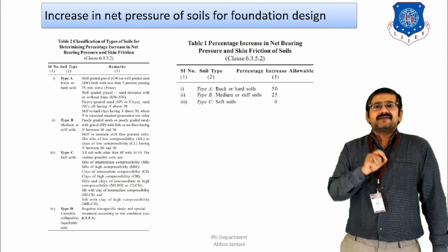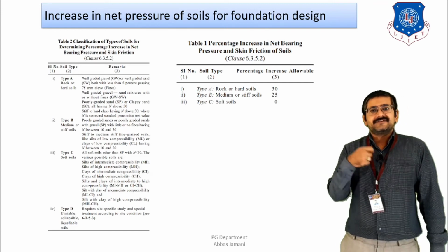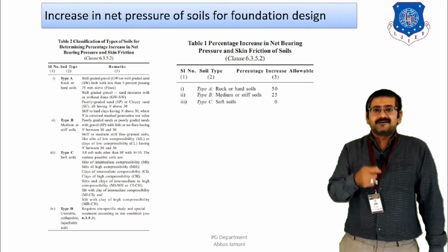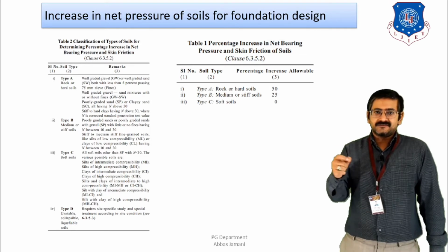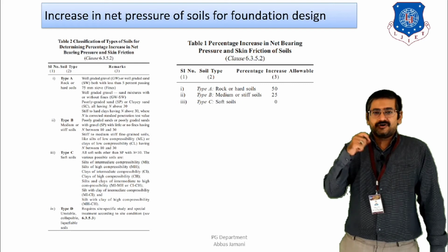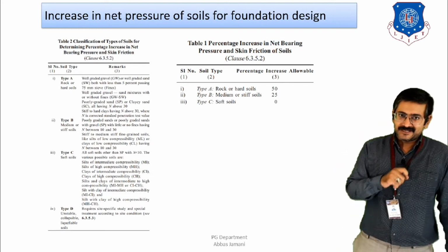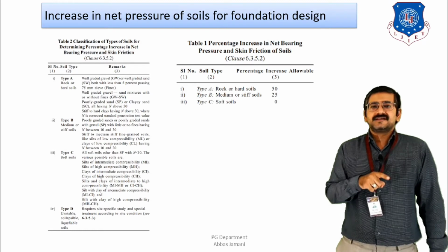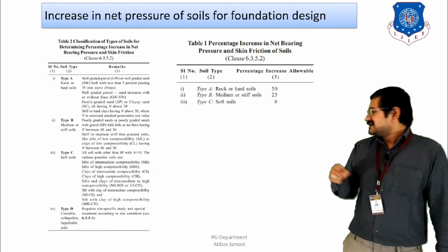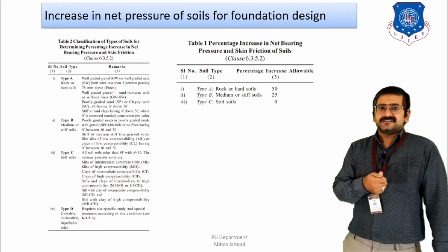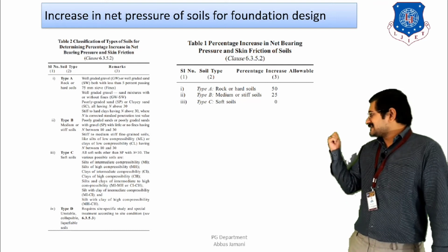However, if I have the second load combinations where the effect of earthquake is present, that is dead load plus earthquake or dead load, live load plus earthquake, then in all these unfactored load cases, which have to be kept in mind, I can increase the value of SBC. That is, I can increase the value of SBC based on the soil strata